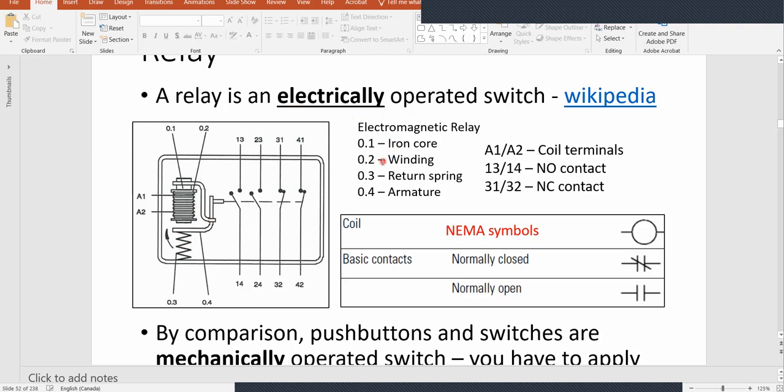A timer is the same thing. With on delay, it's easy to understand. On delay means that when you apply the power supply to the coil, the action is postponed. The contact will take some time to change from open to close, or from close to open. That's on delay, and it's not very difficult to understand.